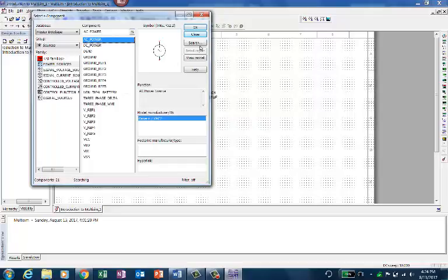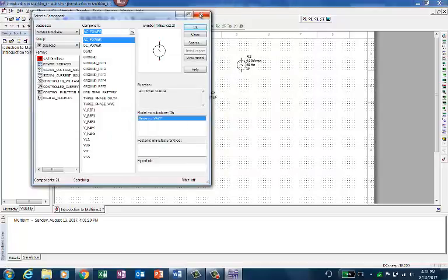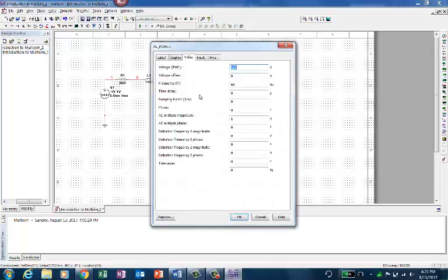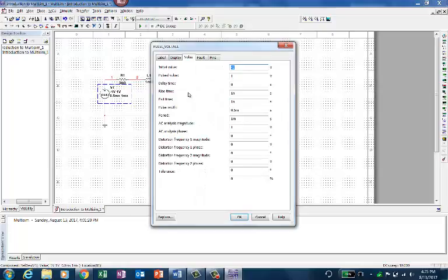If you look through that power source, you define your RMS voltage, you define your frequency, and then do the AC analysis of that. You can do that, right? Let us take this one. We want an initial voltage, say 0.